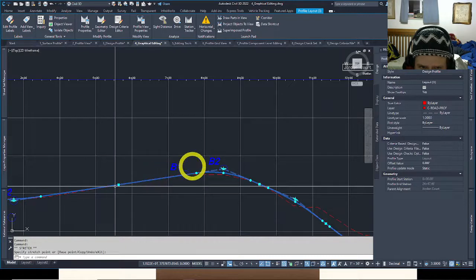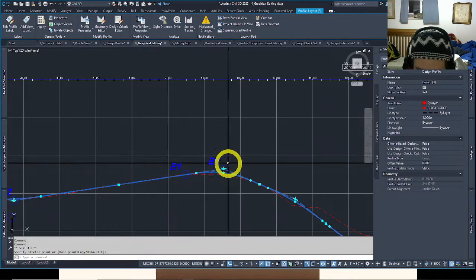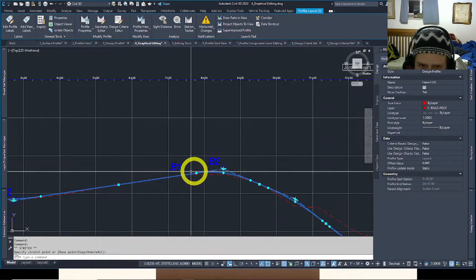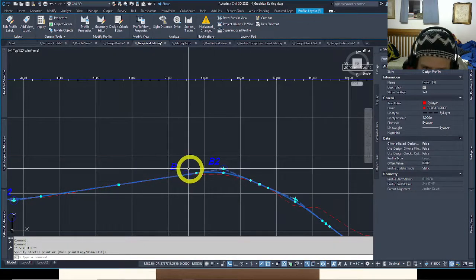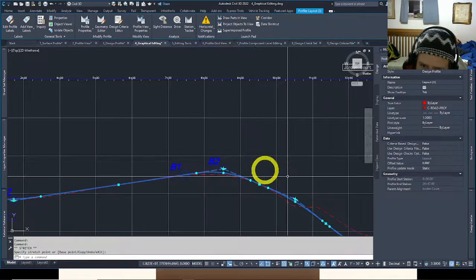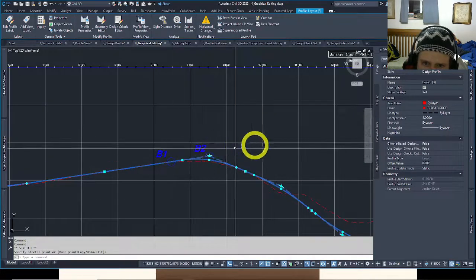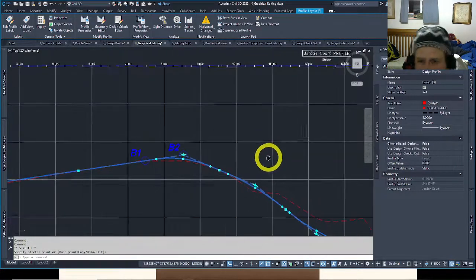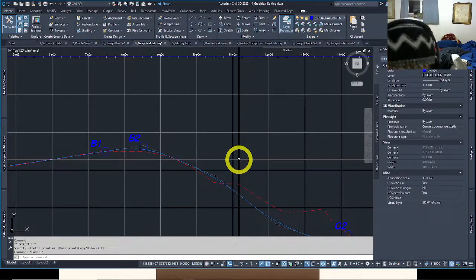You have different things to be concerned about as you're driving along. Say this is a road. You have a sight distance. You have a blind edge here. You also have, you ever done ski jumps before? You go so fast on these, you fly right off the top. So a lot of times you have to have certain vertical curves to control your design speed so you don't literally just shoot off the top. That's a big thing with transportation. So we'll talk about that in a bit.